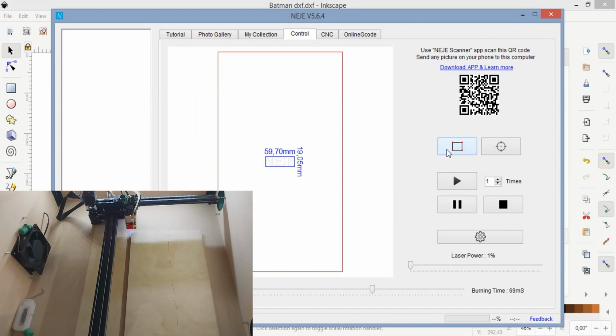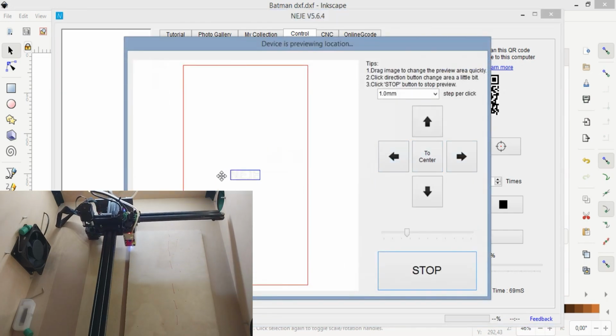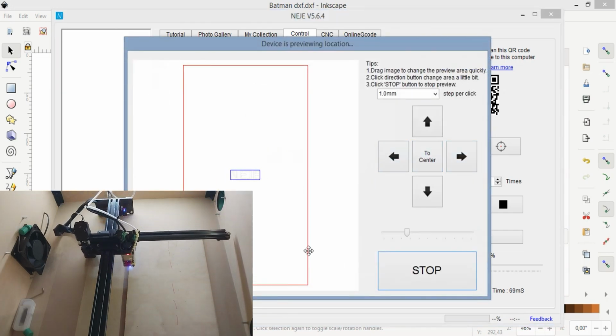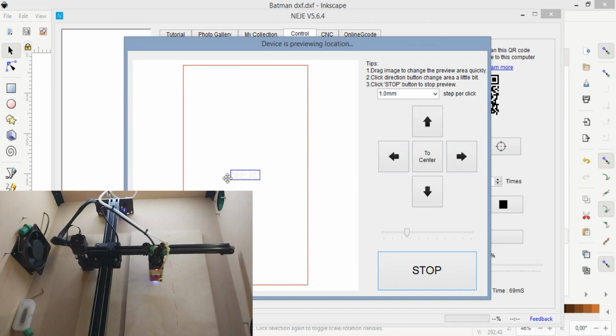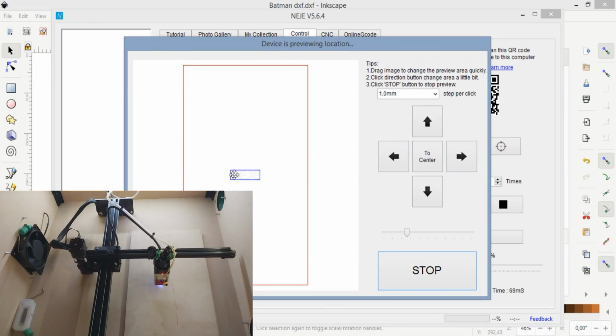Right, so typically if you had a workpiece or a piece of scrap material, which I've actually got on the laser at the moment, and you wanted to engrave something on it, then the framing tool is a really good tool to help you do that. So if I click that, it tells you that based on the size of the machine, this is where it's going to engrave, and it actually places that engraving in an area to show you.